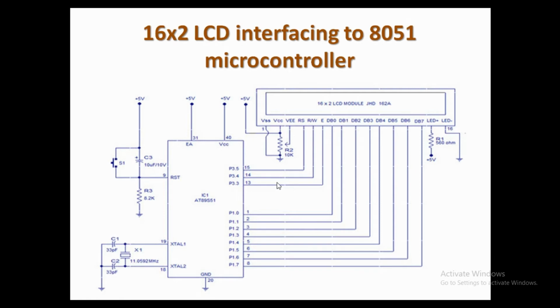This is the kind of configuration I'm going to be using in my project, so that's how I've used this pin, but it can be connected to any other pin. But now I'm going to be using the third port, therefore that's why I've used this as my demonstration. Then this one, DB0 to DB7, is a data bus usually used for transferring information from and to the screen.